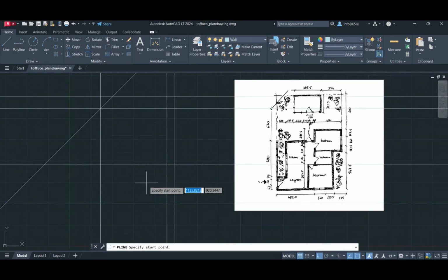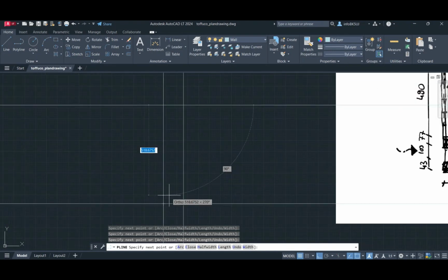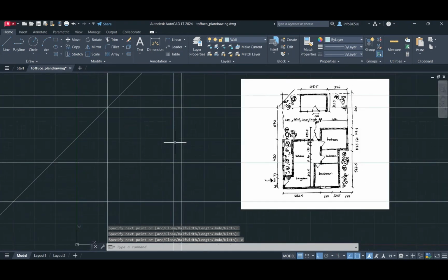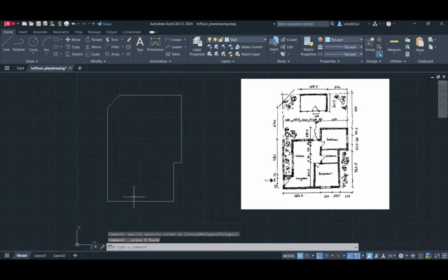We draw the borders we set with the Polyline command. The reason why we use the Polyline command instead of Line is that we will draw continuous lines. With Polyline, we draw our walls with reference to the dimensions written in the sketch. After the drawing is finished, we can delete the infinite line.